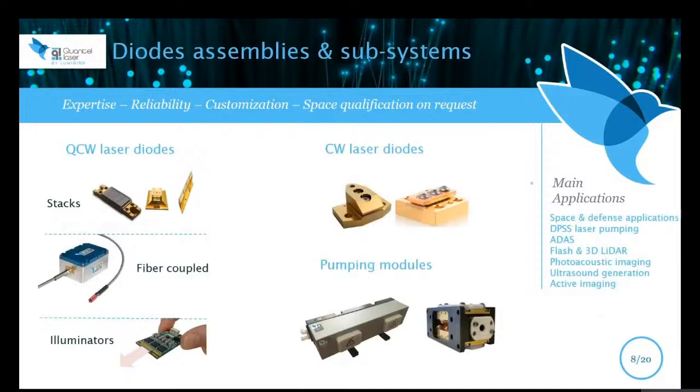For the diode laser lineup, the core product is a diode laser stack, which is used for the optical pumping of the solid-state laser made by Quantel, or for external customers. Quantel is able to offer more than 1,000 declinations of the QCW laser diode stack, tailored to very specific needs in size, in power, or in wavelengths. The wavelengths can cover the range from visible, 635 nanometers, to the near infrared, 1100 nanometers.